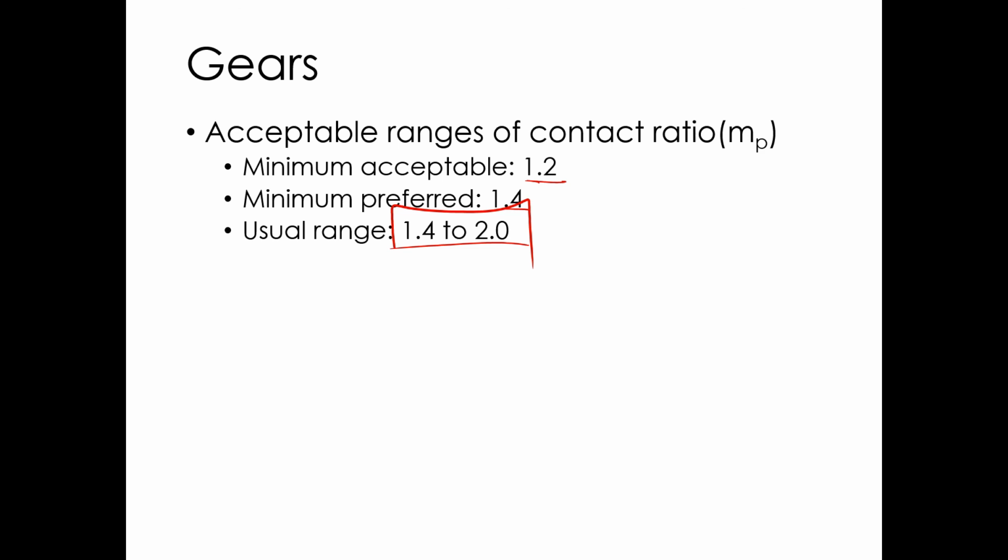Usually they're going to get a little more expensive as the number of teeth go up, just because they're harder to manufacture. So that's how you pick the biggest possible tooth you can get by with. Again, there's not a huge reason to go much past 2. It's hard to get much past 2. So 1.4 to 2, that's what you mainly need to check. That determines if your teeth are the correct size.